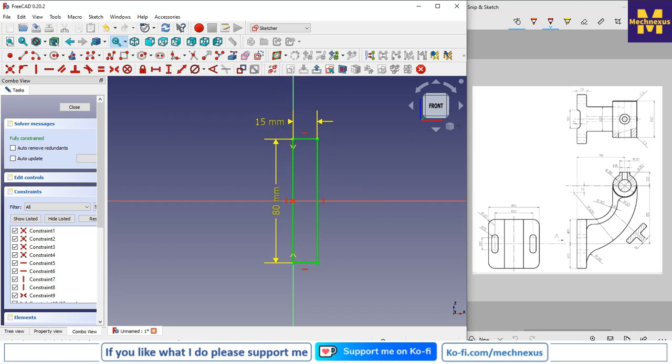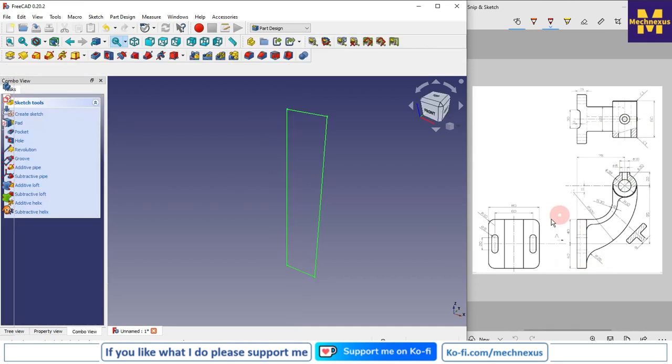Now I will extrude it. The extrusion length is not given in the top view. It is in third angle projection, because we can see the boss here. So I will close it. I will make it 80 by 80. The dimension is given here because it is a third angle projection, so we can get the dimension here. So it is 80 by 80.